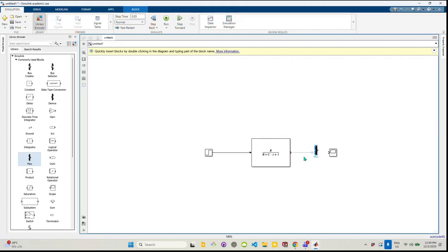Okay, and this is going to combine the two signals and show both signals on the same graph. So I can bring one line from here. So when you reach to this line, right click, and then release the right click button when you reach to this greater than sign.